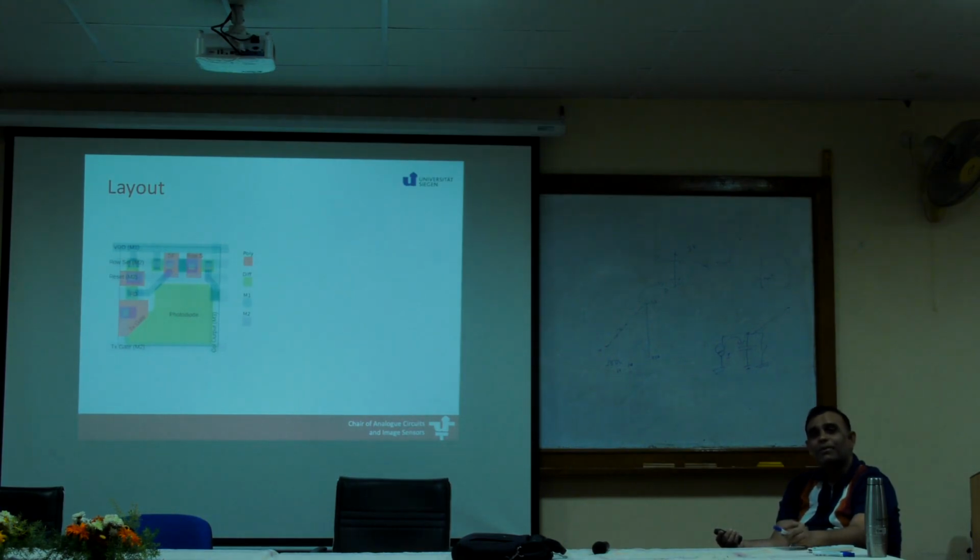That's one of the first problems which we have in pixel design. A lot of area goes into the subsidiary circuit, even though they are just 3 circuits. The other thing which we have to do, we have to give some separation between 2 pixels, or else the diodes will merge. So the gap then also wastes space. This is an advantage which the human eye has. There is no gap between the pixels.